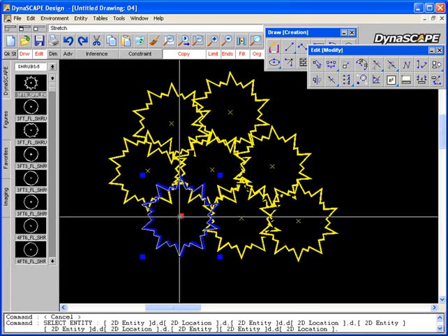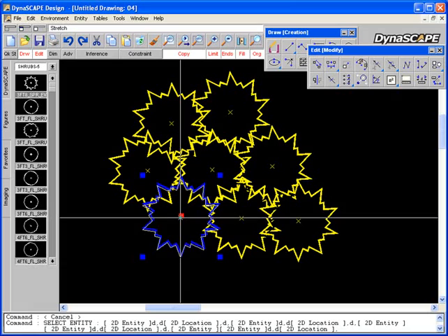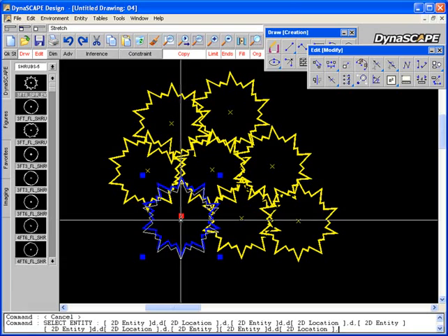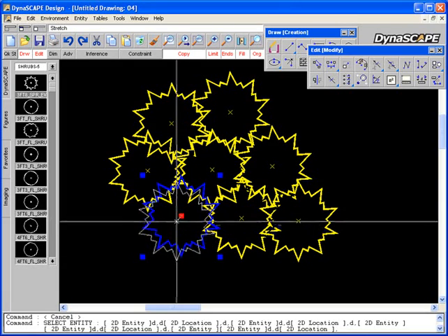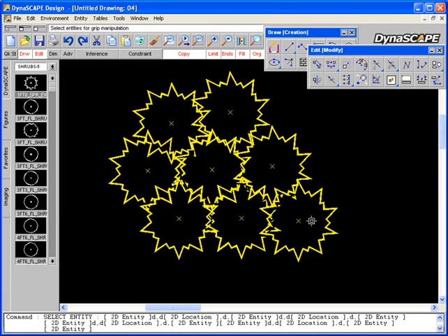And if your inference is on, it tends to prevent you from moving it a short distance because it wants to snap to one of the areas where your grip is, usually the center of your symbol, because you're not moving far enough away. Inference will snap it, keep it in place until you move it further away, and you can't do the fine tuning that you want to do.